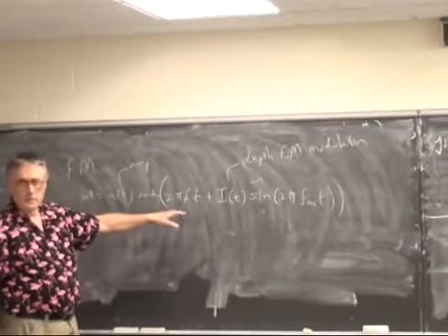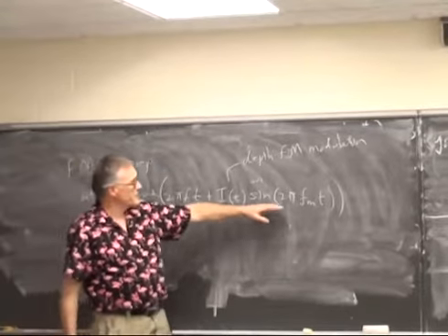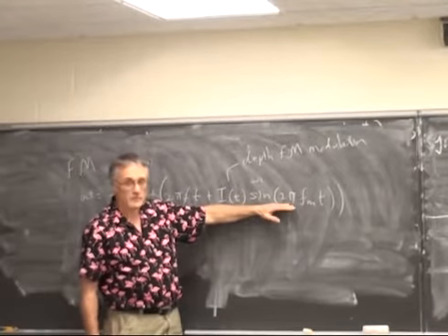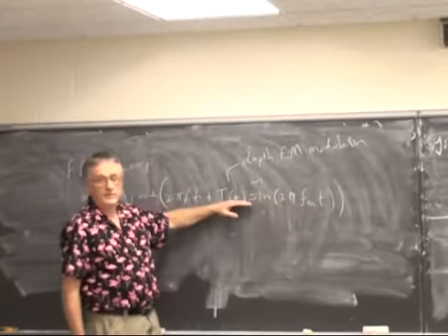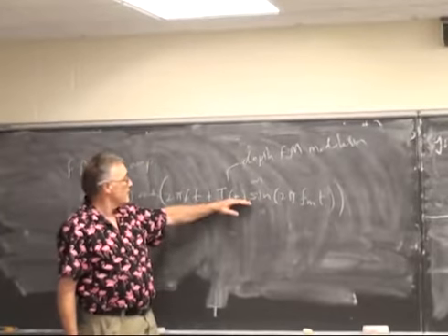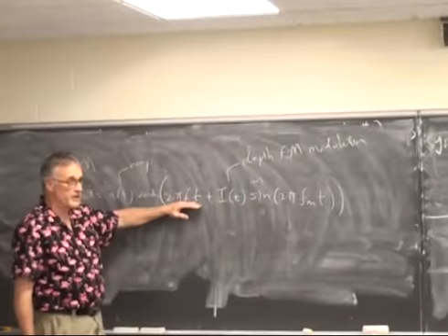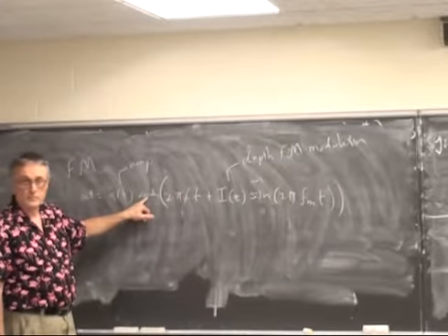So is it clear how you would implement this on the FPGA? You'd have a direct digital synthesis unit producing this sine wave. You multiply it by some envelope, and then you apply that phase plus this continuously changing phase to another direct digital synthesis unit that produces this output.